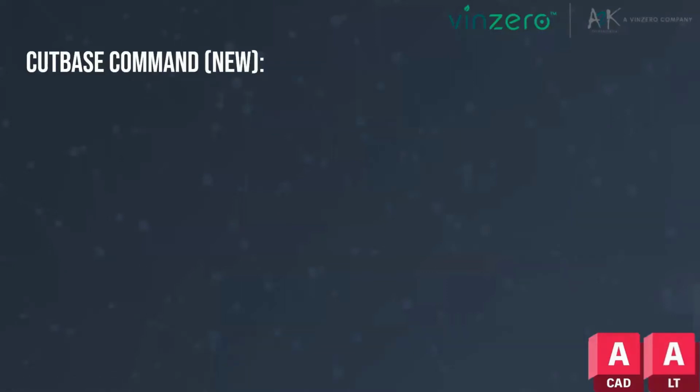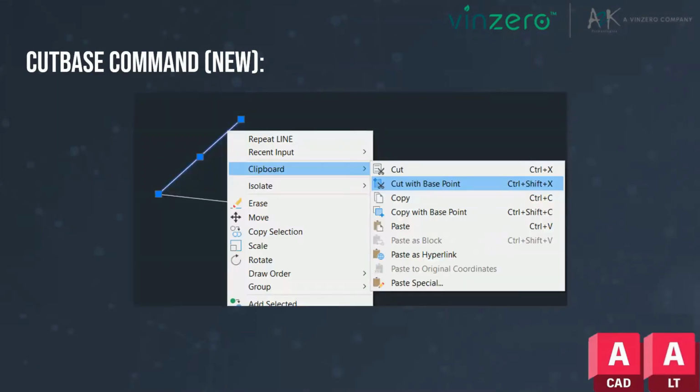Now let me just check I haven't missed anything there. No. So CUTBASE, nothing really massive there. Instead of copy with a base point, we've got cut with a base point. So basically you can cut it out of a drawing, paste it into another one, whereas the one we're used to is our normal copy and paste.